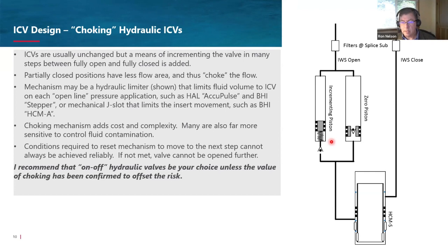And if your production teams and reservoir teams, everyone can get together and look at the value of choking and then agree that there is a lot of value in choking that offsets the risk, by all means run them, and people do run choking valves successfully. But I would never recommend that you run a choking valve just in case it adds value later. If you don't see a clear value in it, always go with an on-off valve.